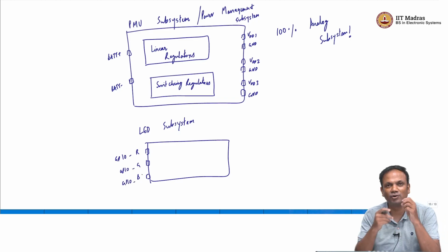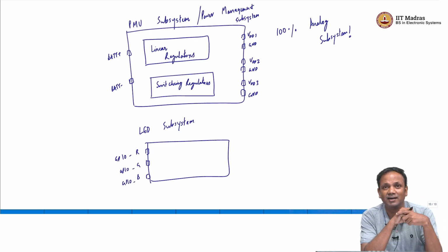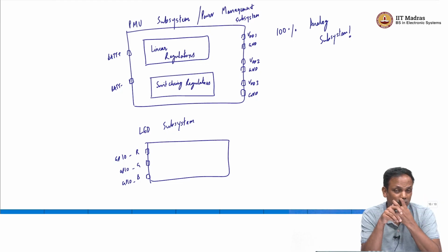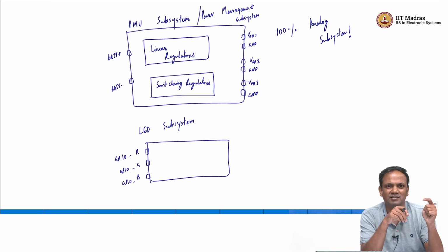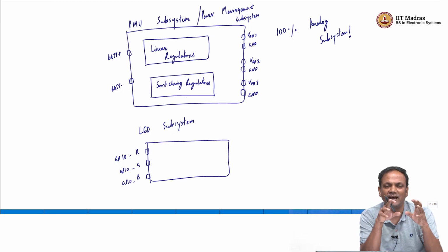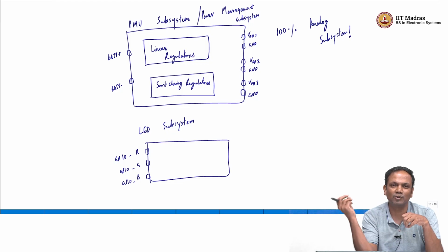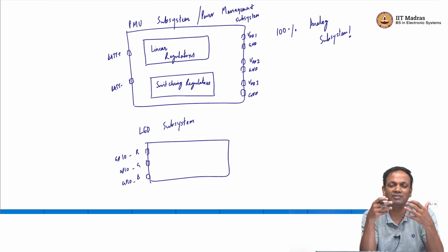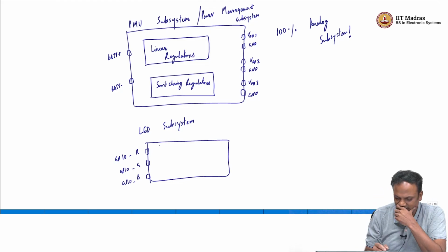So, we have a red, green, blue LED, RGB LED, which is the three primary colors, and each of these LEDs is getting driven by a general purpose IO, what we are calling a GPIO, and these general purpose IOs reside on the microcontroller. So, there is some logic on the microcontroller that says okay, now go flash red. What that GPIO will do is have the digital signaling to be able to produce the effect. It just decides when and for how long which LED needs to be on. So, you think of this as a switch.